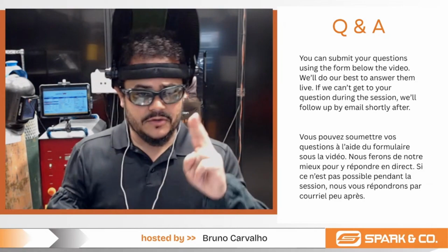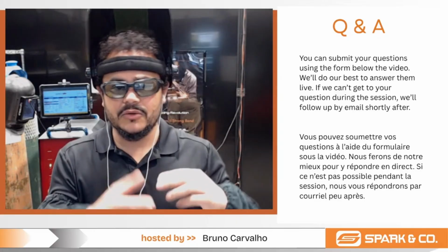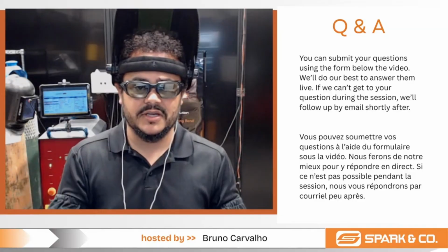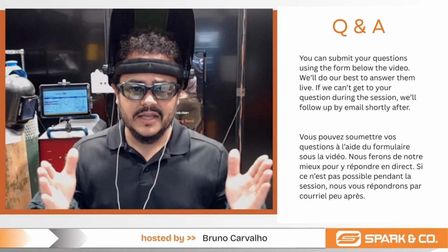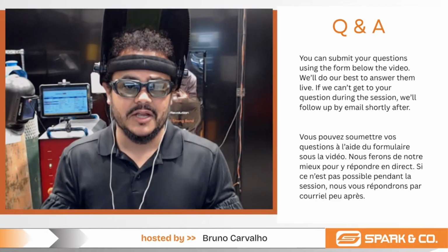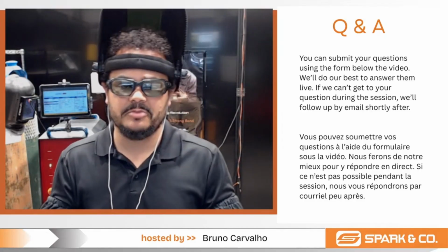It's because if you're using two wires to weld at the same time, you need to adjust the wobble length. You need to have a wider bead, right? Like you just showed here in the presentation, if you increase the wobble length, you have less penetration, and adding another wire means even less penetration. Because of that, you're going to need pretty much double the power to have the same amount of penetration.